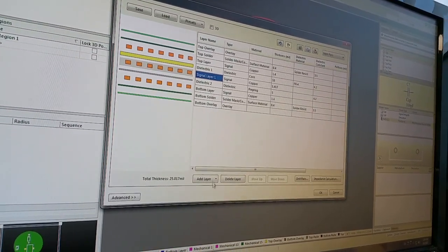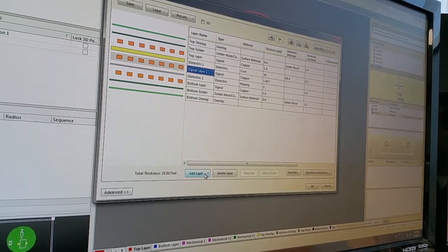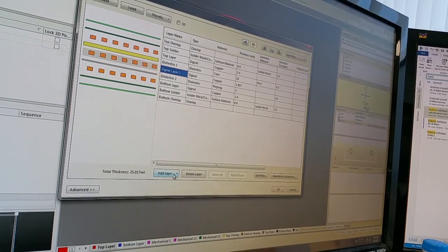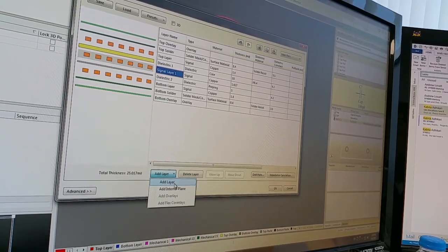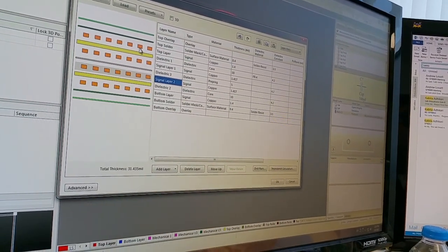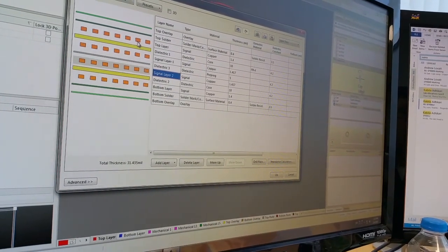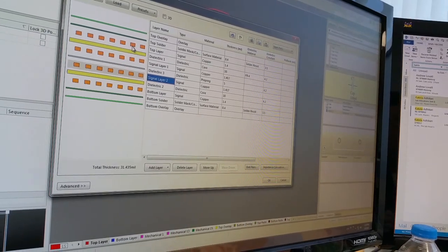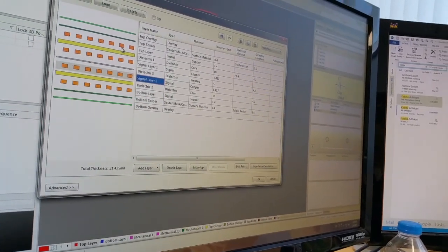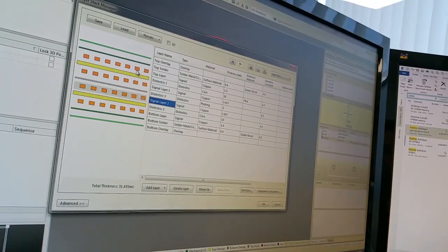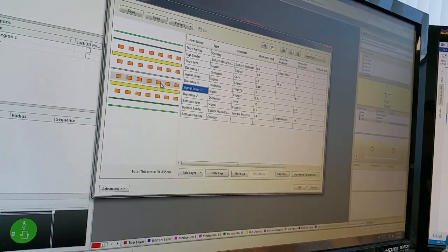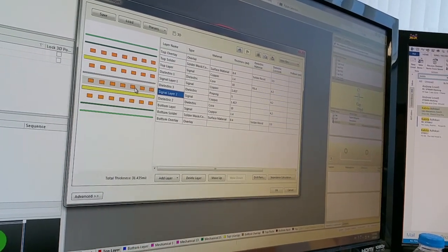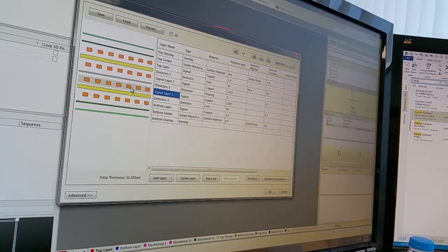So then how can this layer be used for tracking on the PCB? You can use it as much as you want. So make another, so it becomes 6 layers. I think we need to specify this at the beginning of the process. You can change it in the end as well, but before routing. If you do routing and you see you have a problem, you can add a layer, then do the routing again.